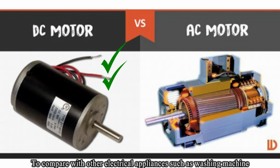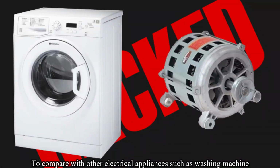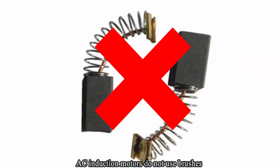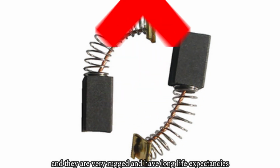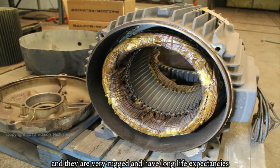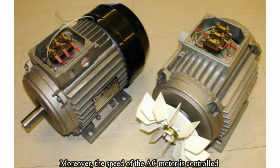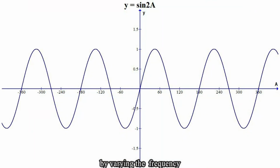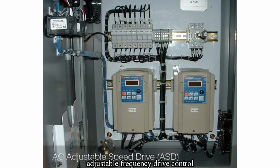To compare with other electrical appliances such as washing machines, its AC motors are powered with alternating current. AC induction motors do not use brushes and they are very rugged and have long life expectancies. Moreover, the speed of the AC motor is controlled by varying the frequency, which is commonly done with an adjustable frequency drive control.